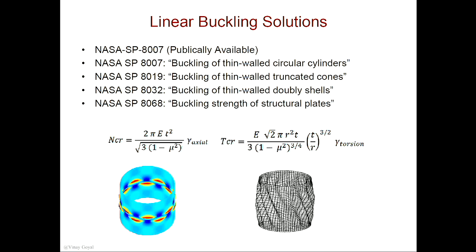If you remember from the YouTube video, the gentleman, Mark Hilburger, was talking about the shell buckling knockdown factor project. You remember him talking about that? That's why. NASA is trying to improve upon those factors that were published back then, and he spoke about that in the video. They're doing that because the knockdown factors used today could be too severe compared to today's manufacturing processes. They also wanted to prove out that analytical methods can actually predict buckling accurately. And that's what I'll show you today, how to do that.